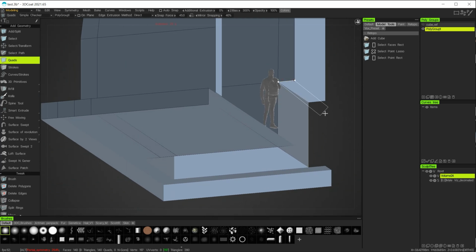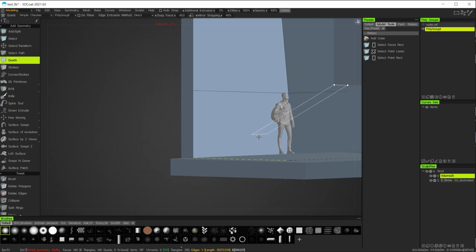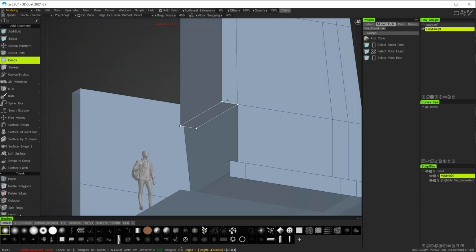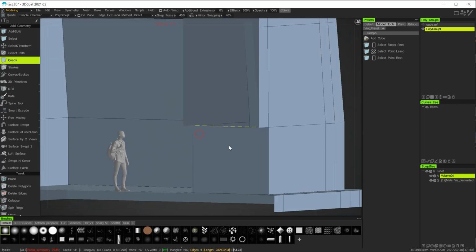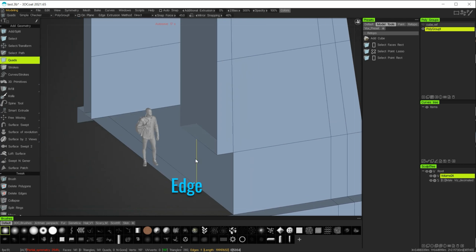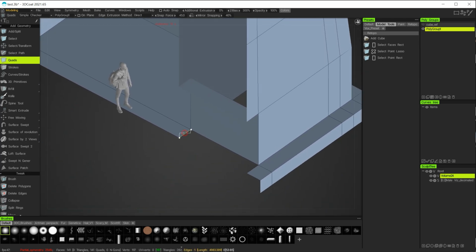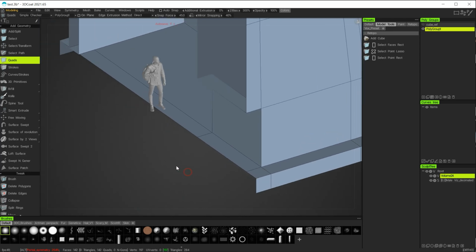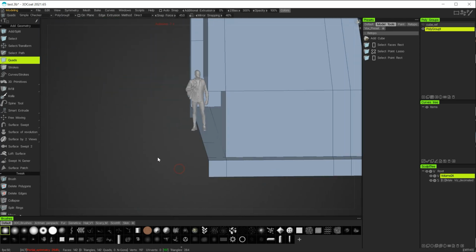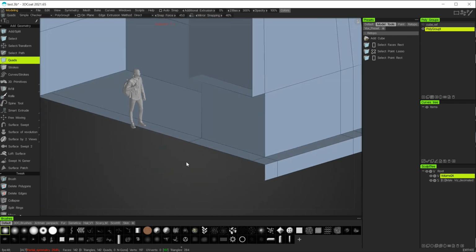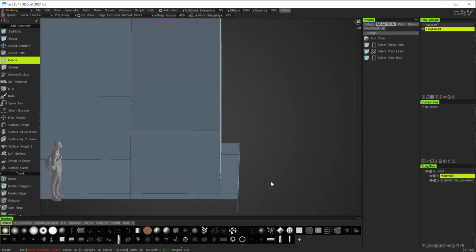I click Alt, rotate the view round, and just make sure I'm there, and then snap it to there so we know I've got a good snap onto that face. And try one more time. This one I don't need to because both normals are facing upwards, so it's easy for me to snap that one. So that gives me that doorway there.